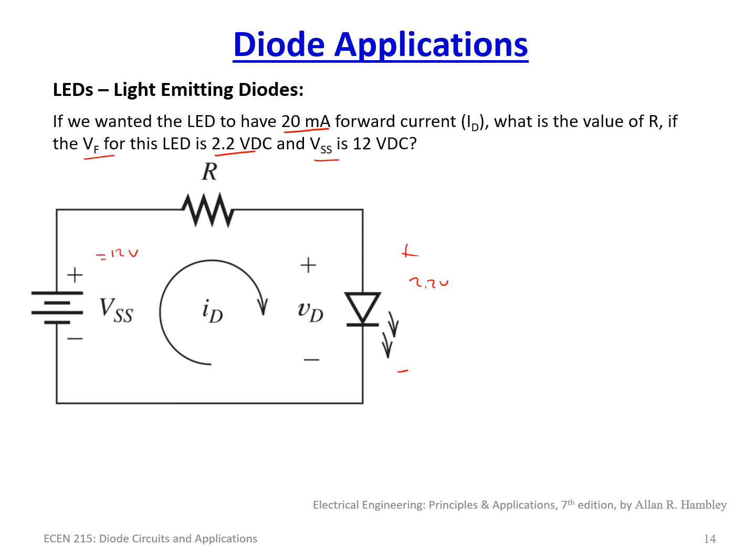What is R? So this diode, again, will light up, and notice the symbol difference for an LED. The only difference that was added was these two little arrows here to indicate that photons are being given off. So that's to let the designer, or someone who's reading your schematic, know that specifically this is being used for an LED application and not just a standard signal diode. So what we have here is a 2.2 volt drop here. We have the resistor R here.